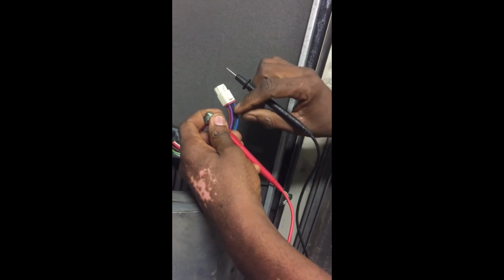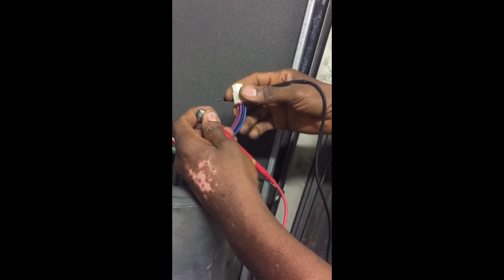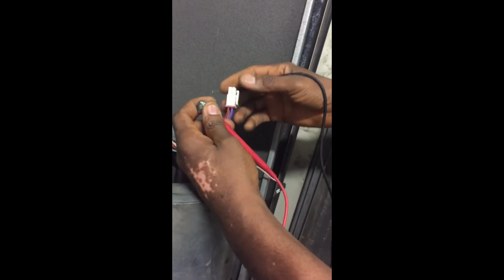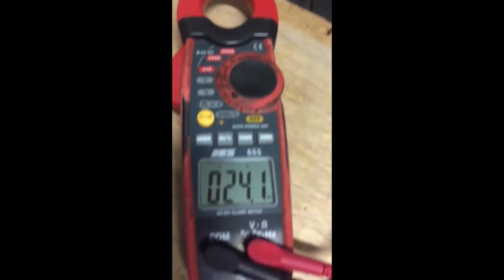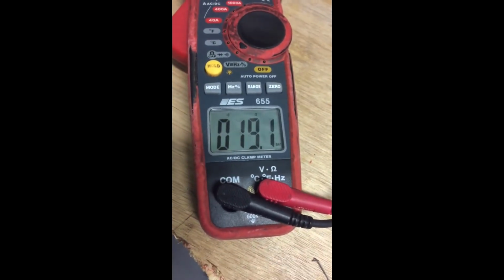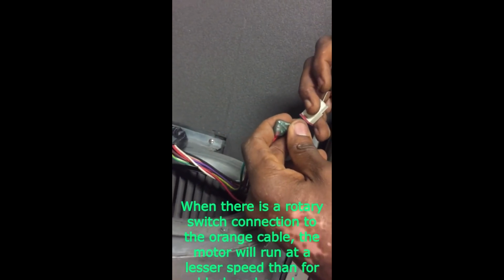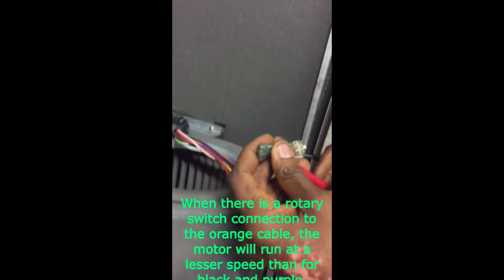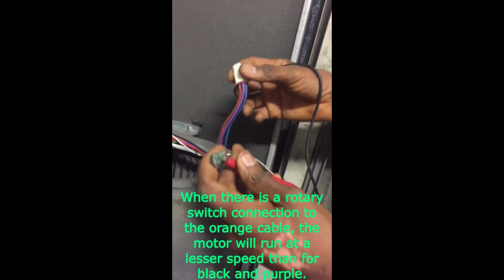There is still a little bit of resistance between the high speed and the run terminal. So at medium speed, which is our purple, we still have a little bit more resistance than you have for the black. That's why when there's a switch connection to the purple, the motor will run at a lesser speed than for black.